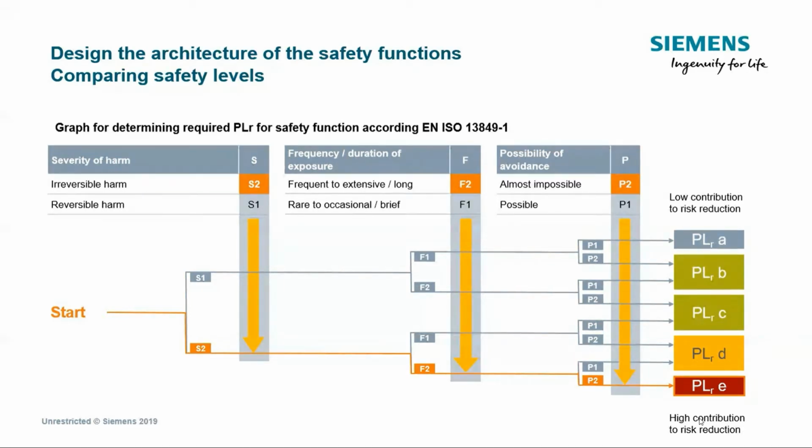And again, when you check our devices, for example, a controller or an I/O system, you see that the certificates issued are based on different standards. So you see that, for example, an S7 fail-safe controller is certified for applications up to SIL 3 level and performance level E. That's the highest level based on the ISO 13849 standard. So they are certified according to different standards. So whenever the user uses one particular standard or another, they can use the same system as a safety system.